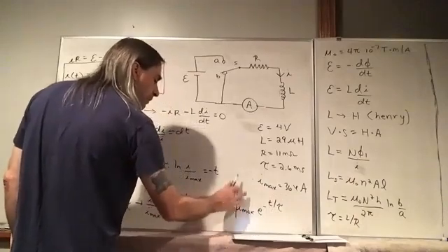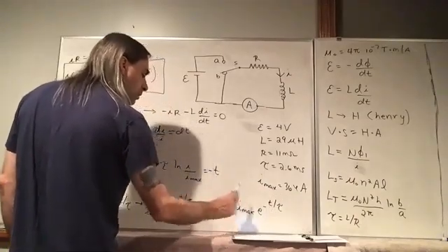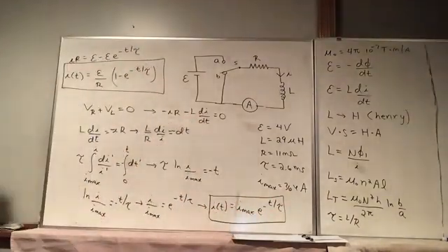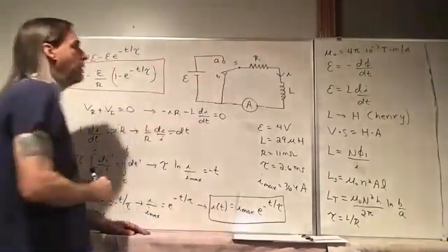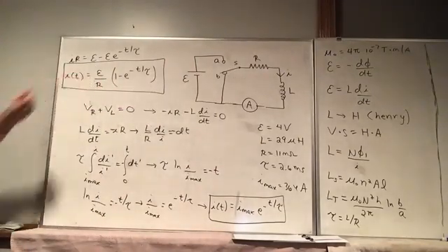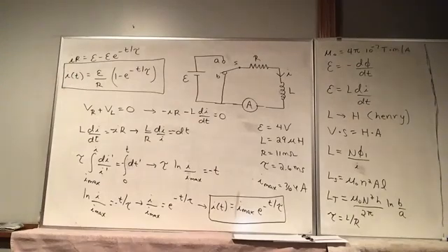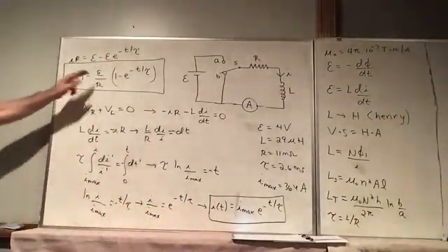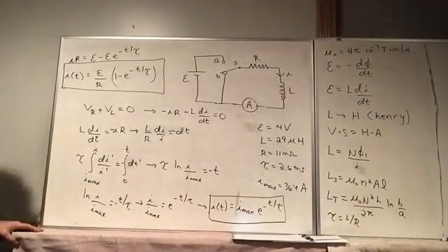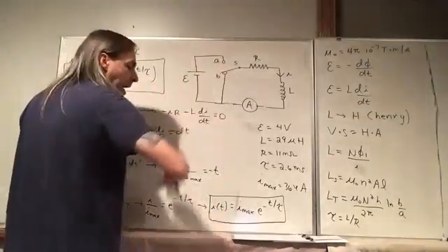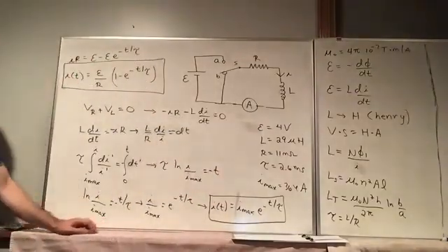Kind of similar to what we had before. When we start out with no current, we flip the switch to A, and the current rises up to its maximum value, epsilon over R. In a short time, it'll reach its steady state of epsilon over R. Once we're at our maximum current, we flip the switch to B, and now the current decays according to this equation.